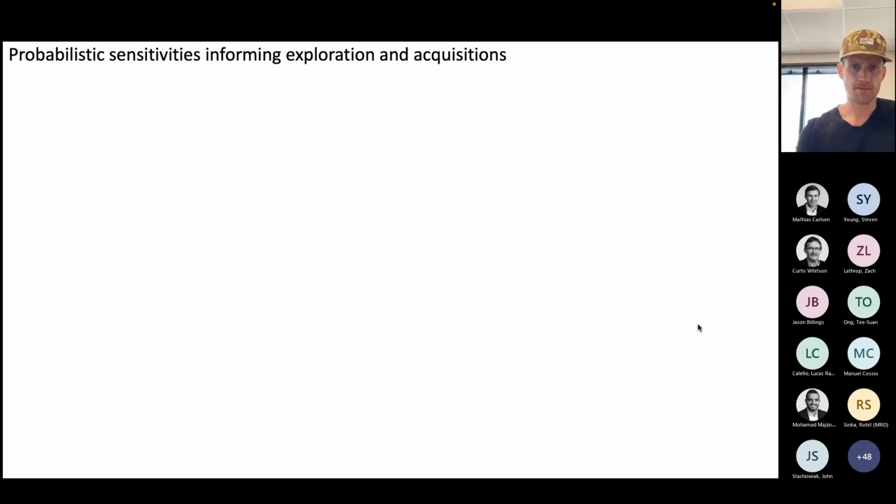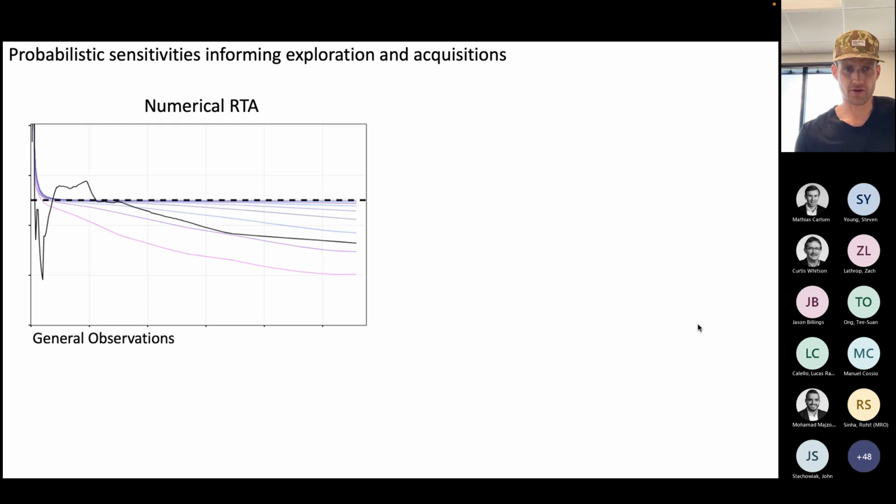So we're using numerical RTA. Here are the standard plots we're used to seeing. What I'm generally working with is FCDs that are much lower than the infinite conductivity that we've been told to use in the Apache papers. I'm looking at an FCD of 1 to 5. When we're in our higher nanodarcy reservoirs, the 1,000-plus nanodarcy, we sometimes go up to 5,000 to 6,000 nanodarcy. And then I'm finding better matches within our system with an FCD of 10 to 20 or plus, since we're relatively infinitely conductive there, when we're in the 100 to 1,000 nanodarcy.